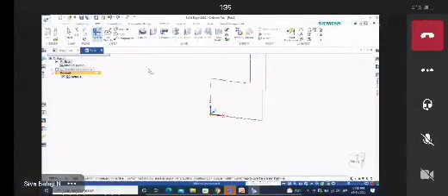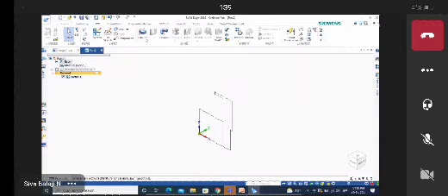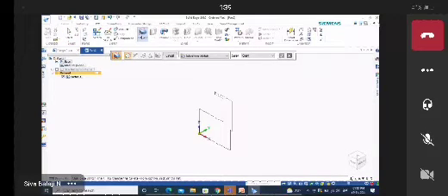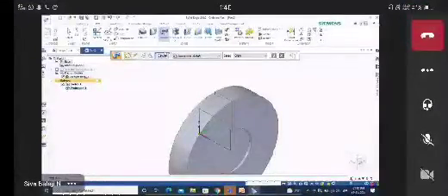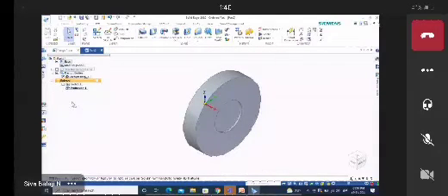Now you can close sketch, finish, cancel. Now you can convert this diagram into 3D. So you can close the 2D sketch and select the revolve command. In that you can check whether select from sketch is there or not, and you can select this profile and accept this one. It is asking chain, you can select this line, finish, cancel. Okay, now you can switch off the sketch.